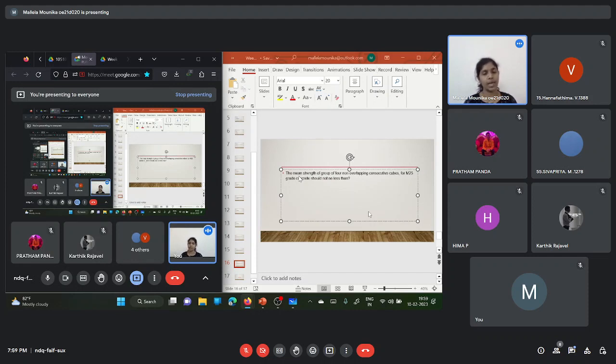This concept also relates to the characteristic strength value concept only, because if you take four cubes of concrete, and for M25 grade we have done the design for this M25 grade concrete, and you have cast different cubes out of the concrete, and if you test the four consecutive cubes, then the grade of the concrete should not be less than 25.